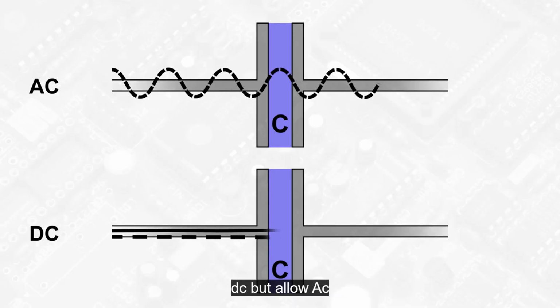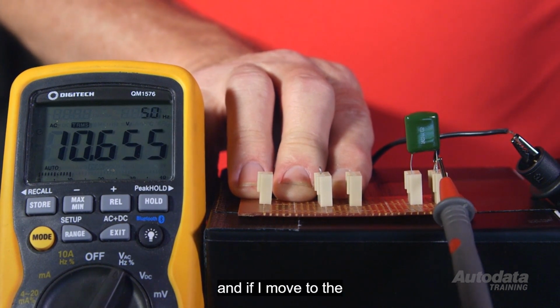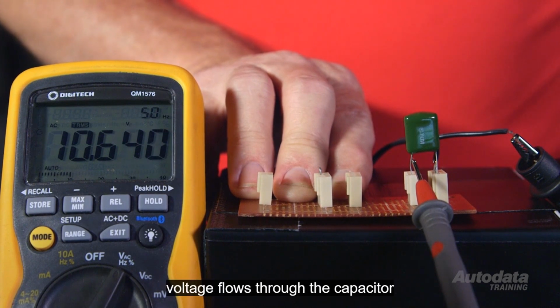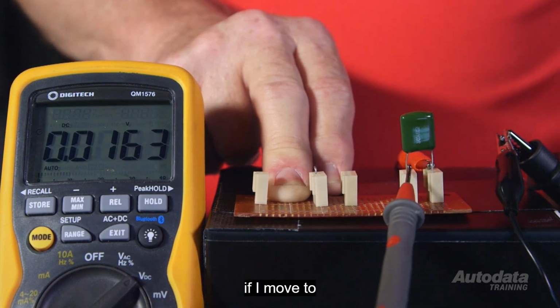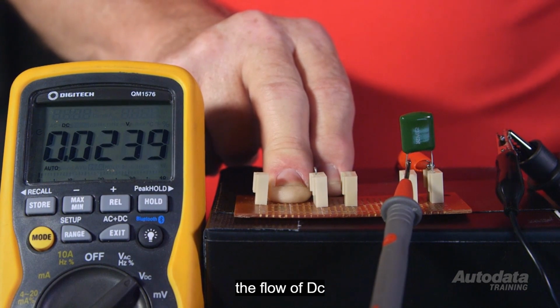They block the flow of DC, but allow AC to pass through. I've got here an AC power supply hooked up to a capacitor. I've got just over 10 volts AC. And if I move to the other side of the capacitor, you'll see that I've got the same AC voltage there. The AC voltage flows through the capacitor. This time I've got 12 volts DC connected to the capacitor. If I move to the other side, you can see there's virtually no voltage. The capacitor is blocking the flow of DC.